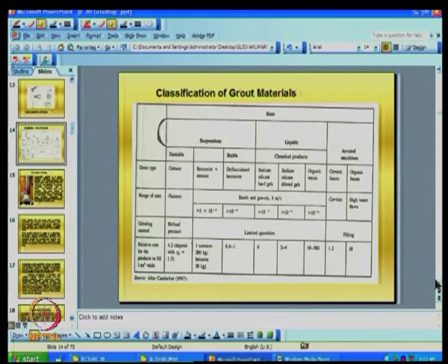So, we should be able to understand what are the different types of suspensions or grouts you have, since you have seen that there are 3 or 4 types here. For example, as I just mentioned, the state of the grout could be in the form of a suspension, it could be in the form of a liquid, or even in the form of aerated emulsions or foams. Grout type, say for example, suspension type, is unstable and stable. I will discuss that later, what is stable and unstable.